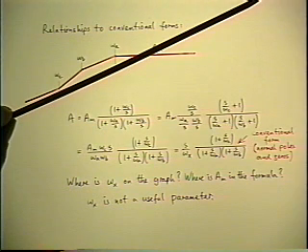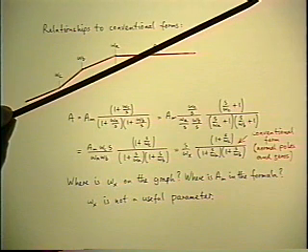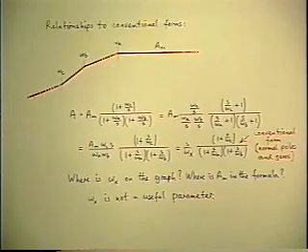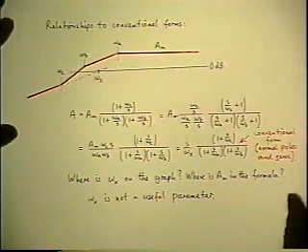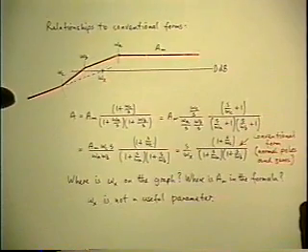Remember the special case we've had already, where there was no flat gain and we identified a single slope asymptote by identifying the gain at a specific frequency. This is a special case of that. Right. Omega x is the frequency where the zero frequency asymptote crosses 0 dB, or unity gain magnitude. So I could draw it like that.